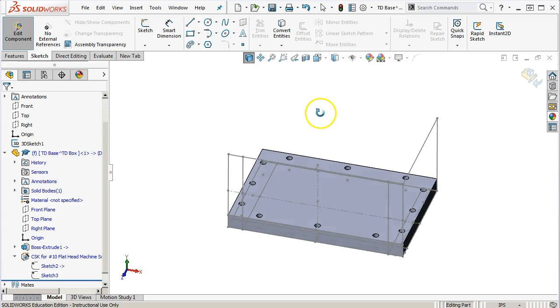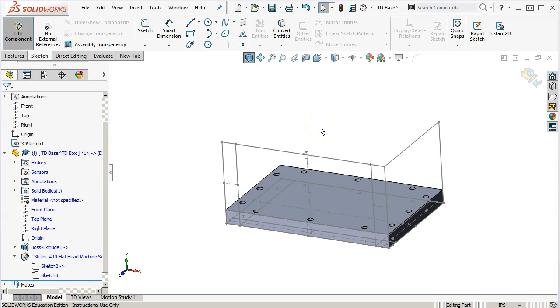But once you start going through, and I don't know how many extra points I'm going to have in that 3D sketch or which one's going to cause it to fail, I can remove that point, I could remove that point, and it would probably be okay. But then I go back later on, and I'm setting myself up: oh, I need a couple more holes over here. Well, I put those couple more holes in, it comes back to this feature, it tries to put them in, and then it fails. Do I remember, or somebody that has no clue what I'm doing opens it up, oh yeah, I'm just going to make this simple change, and then I create a big quagmire for them. So there's a crossover point of is it practical and is it reasonable?